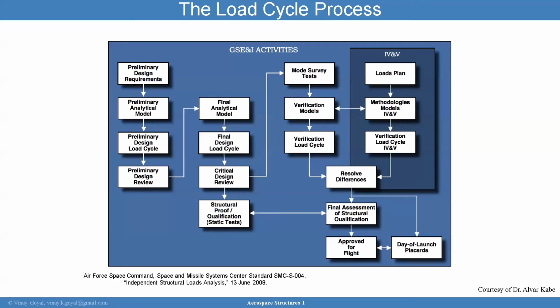You also have spacecraft components like appendages. Say you have an attachment like an antenna. Those tend to be modeled, but tend to not correlate very well with test data. And so again, it's very important to consider these points because that drives the loads that you need to then test later. And if those loads are incorrect, then you're going to have a significant issue with the design.